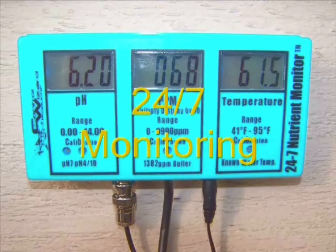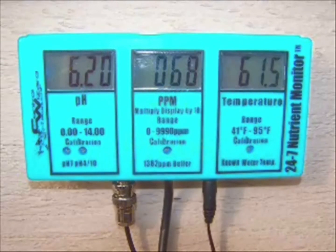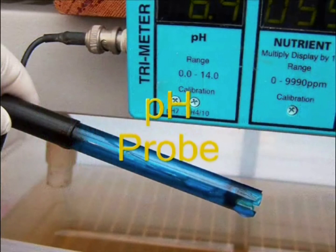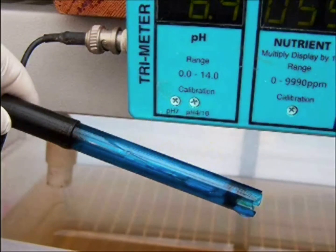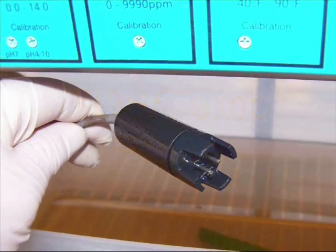pH, TDS, and reservoir temperature can be monitored around the clock with this type of equipment. This is very convenient, especially for larger, more permanently located systems. This system consists of an indicator panel, a pH probe, and a combination TDS temperature probe. These are left in the reservoir and removed for calibration and cleaning if needed.